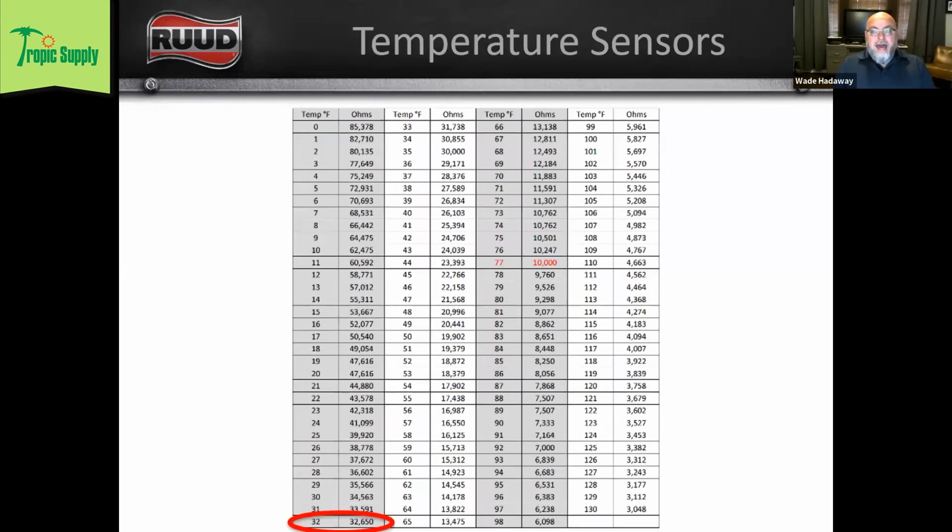So at 35 degrees, it's going to struggle. And I'm talking about a single stage conventional heat pump, right? If you want to talk about inverter systems, we can go down to 0 degrees and still be efficiently pulling heat out. But on a RP14, about 35 degrees is where it starts to struggle. We start to hit that balance point. That doesn't mean that at lower than 35 degrees, it can't pull heat out of the air. It just starts to struggle.